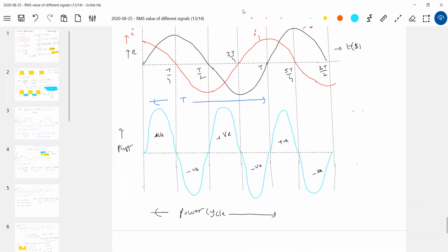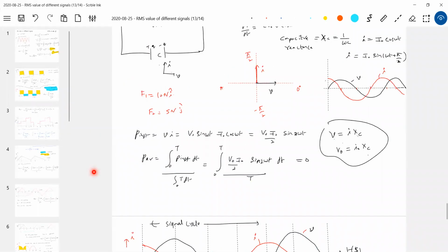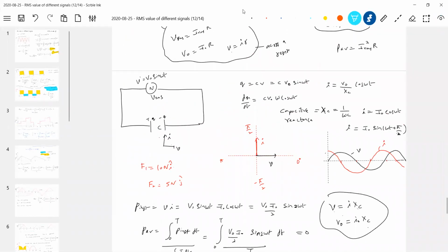So what is the role of the capacitor now? It will just make current lead the voltage by 90 degrees. So therefore we have brought in that reactance. Of all, this is very important. And how do we apply Ohm's law across a capacitor? Not IR, but I into XC. The drop across the capacitor should be like this. Voltage and current are not in phase; they are 90 degrees out of phase. The current will lead the voltage by 90 degrees.